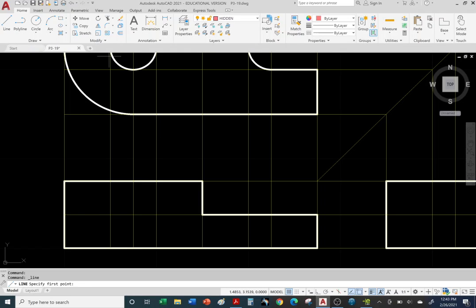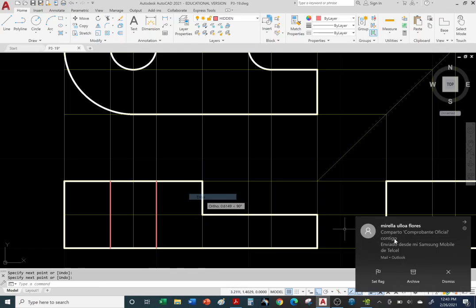And again, from the left quadrant of the hole in the top view, we can come straight down and draw our hidden line. Let me turn on ortho. Hit escape to exit. I'm going to use the same command again, so I'll just hit spacebar. And from the right quadrant of the hole, come straight down. Okay, there it is. Right click enter.